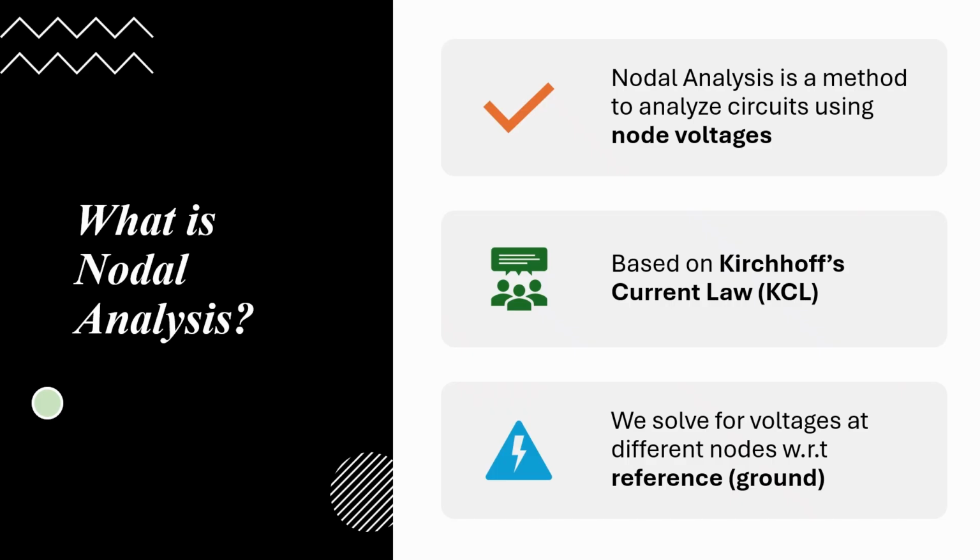Let's start with the big question. What exactly is nodal analysis? In very simple words, it is a method where we find the voltage at specific points in a circuit, called nodes. The whole thing is based on a very famous law called Kirchhoff's current law.